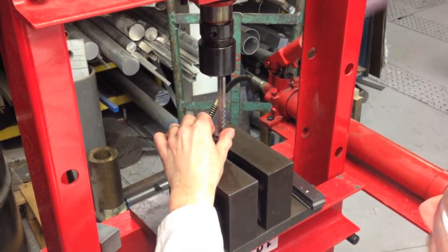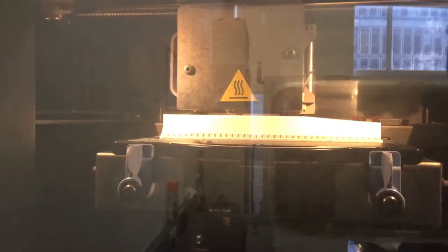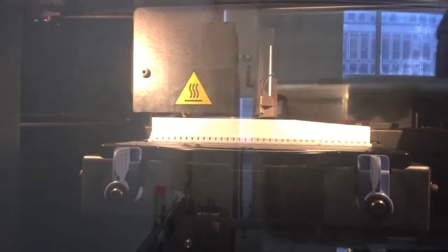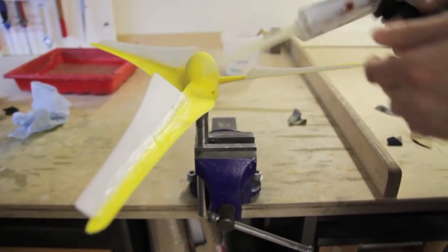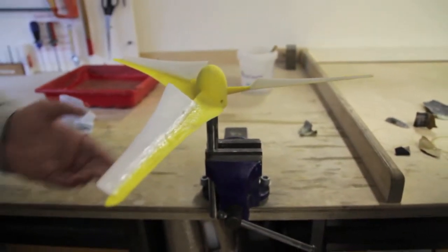The nose cone and the wind turbine blades were manufactured using a rapid prototyping machine and a process called fused deposition modeling. The STL file from CAD is imported into software which mathematically slices the components, and then the material is deposited in layers until the 3D model is completed. In the workshop, we assembled the multiple parts by gluing them together, and afterwards we sanded the whole structure to remove remaining glue and improve the surface finish created by the prototyping machine.